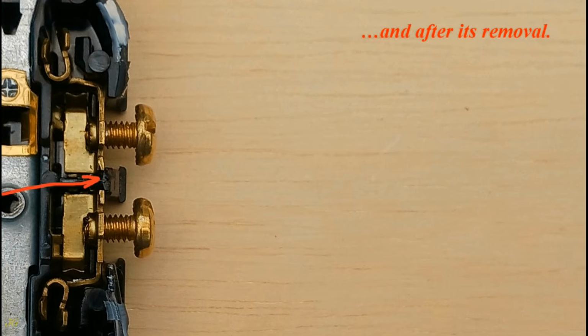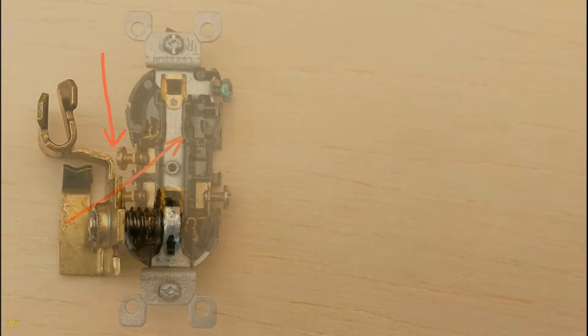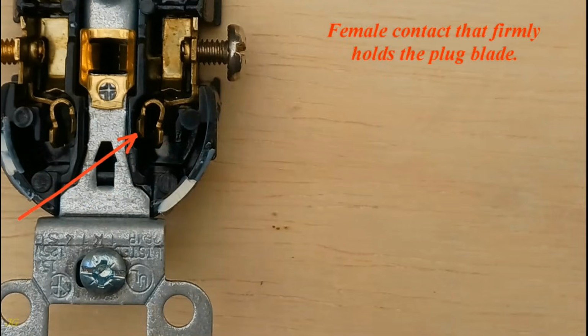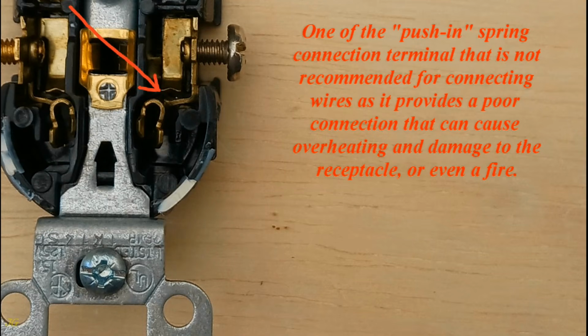And after its removal, female hot contact removed from its base. Female contact that firmly holds the plug blade. One of the push-in spring connection terminals, which is not recommended for connecting wires as it provides a poor connection that can cause overheating and damage to the receptacle, or even a fire.